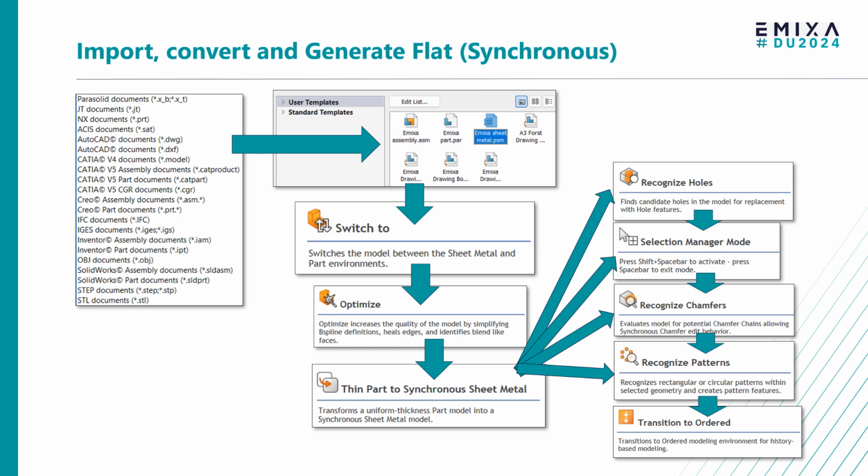So what we tend to do, quick little process before we do the video, is open it as a sheet metal file. It's not really a sheet metal file yet, but we want it to be a sheet metal file, because one thing that Solid Edge does, it allows us to filter via sheet metal file, where if you go to most of the CAD systems, there's just a PAR, a PRT, a SLD PRT, or whatever it is, and the sheet metal files can't be just easily found, especially in Windows Explorer.